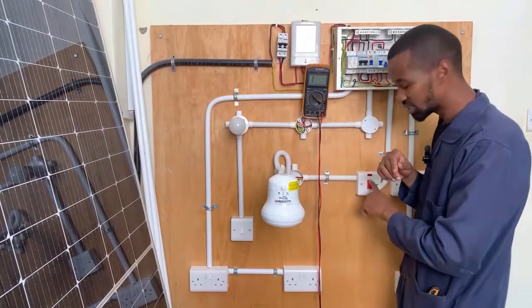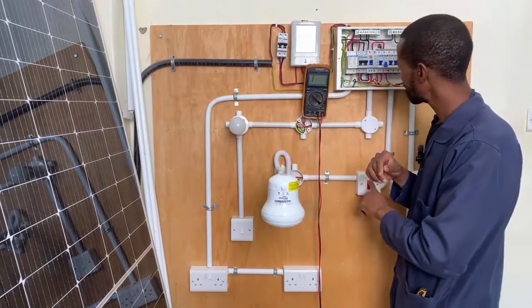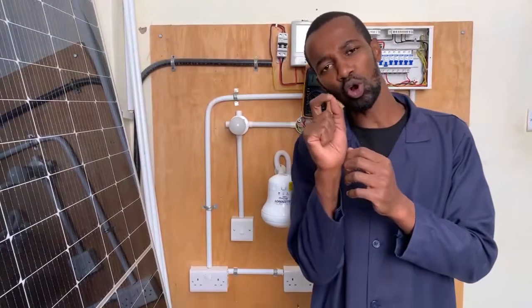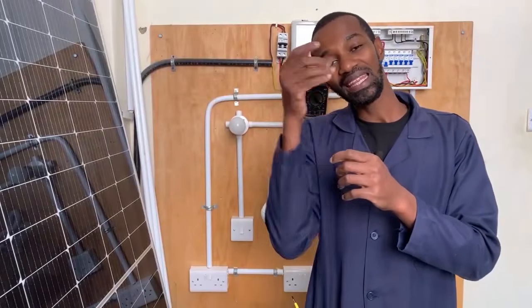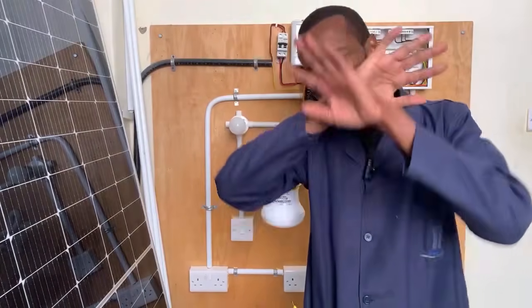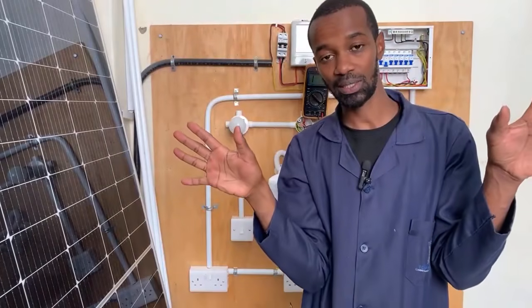Simply isolate at this particular point, switch it off. Get to the consumer unit, it is still off. Measure the output continuity between the line that is supplying that circuit and the neutral. That is usually the first suspect.